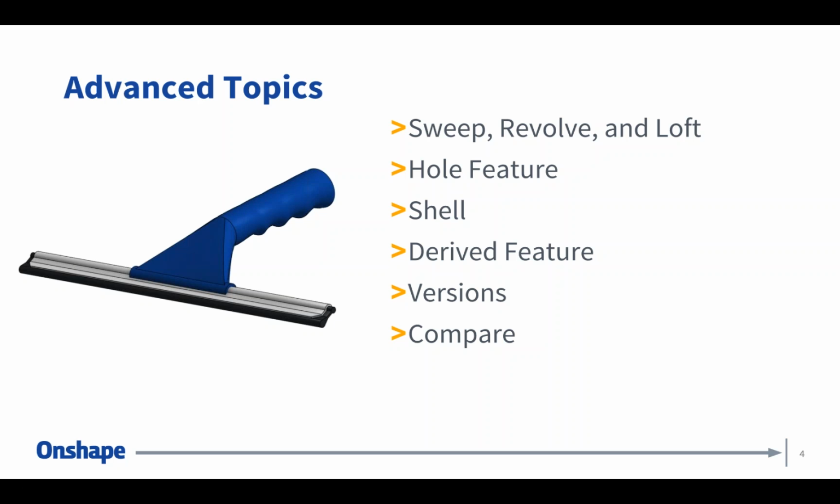Is there a way to transfer an Onshape model from one account to another? Yes. If you go to the share dialog, you can transfer the owner. That's an option in share. And so you enter their email address, you define them as the owner, and it will transfer the ownership of that document to the other person. So the key thing there is it's in the share dialog. Make sure to specify them as owner if you want to transfer the ownership of a document.